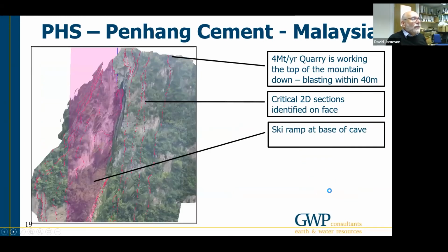So what we were tasked with looking at is the overhead beam here. First of all, looking at small blocks, with the possibility of them coming away, and then also commenting on what would be the results of a large crown pillar failure if that whole section of the upper slope was to come away, and that was quite a few tens of thousands of tons of material.